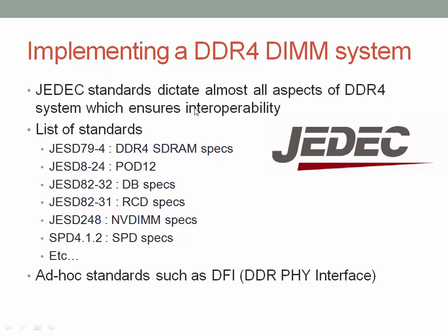So how do we implement a DDR4 DIMM system? Well, it's all about the standards. JEDEC has standards for almost all aspects of DDR4 system design. So here there is a list of standards. It dictates almost every aspect of it. And then there are ad hoc standards created by the companies themselves, like the DFI, the DDR PHY interface, which are used to make sure there is interoperability between different PHYs made by different companies.